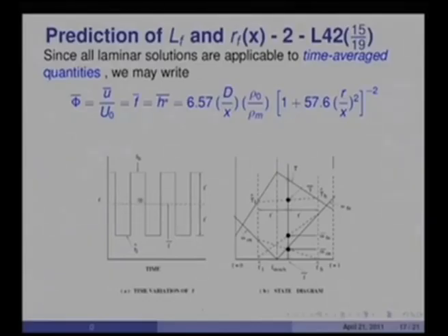So, f is equal to f mean plus f dash on the positive side and minus f dash on the negative side. So, f dash can be both positive and negative around f bar, and this is what I have shown here. So, although the f stoic of the fuel, which is 1 over 1 plus R S T, resides somewhere here between f equal to 0 and f equal to high. So, the instantaneous high value may be here, the average value will be in between the two, but that may not equal f stoic. The average value of f may not equal the f stoic value.